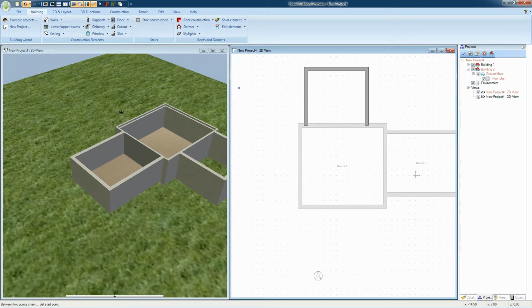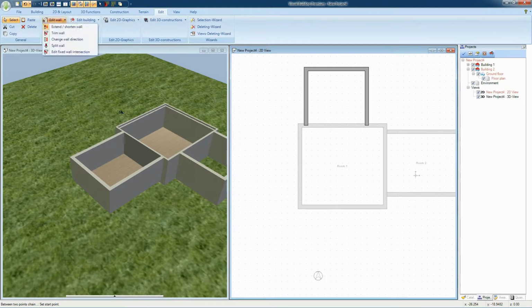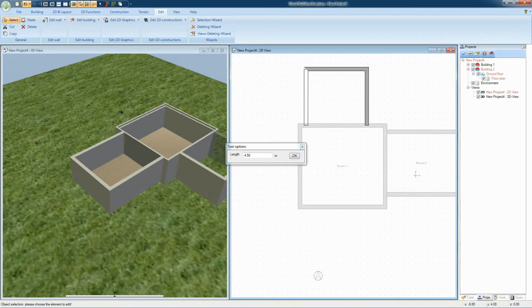With the new second building selected as our current building, we will insert some walls and then cut them back to ensure that they don't interfere with the existing walls by existing in the same place. We do this by trimming back the walls and then again adding a room boundary.